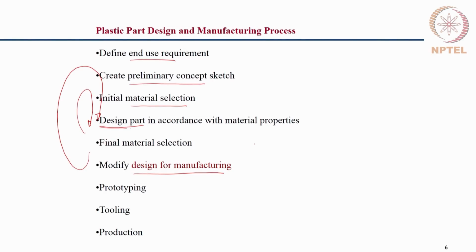once the design is fairly mature, we go ahead with prototyping and then developing the final tooling, because here we are making the tool and thereby we are incurring the cost. So, this step is very critical. We cannot typically go back to design when we are here, and then we release the mold for production.